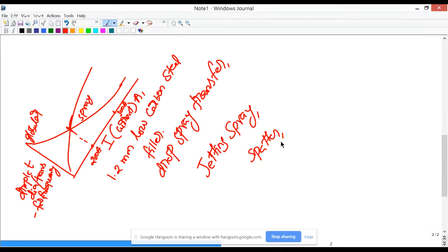in the flow. And imagine you also have an enormous amount of Lorentz force induced inside this spray, plus the magnetic force generated by the increasing Lorentz force, which can lead to unstable pressure creation inside the spray, and that leads to the explosion of the droplet. That's what is known as spatter. So the severe spatter happens when the current is increased much higher than the spray transition current.